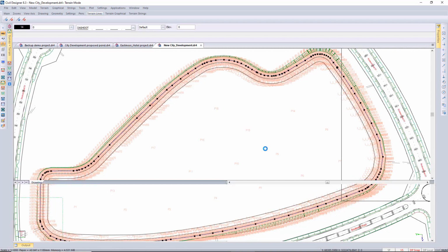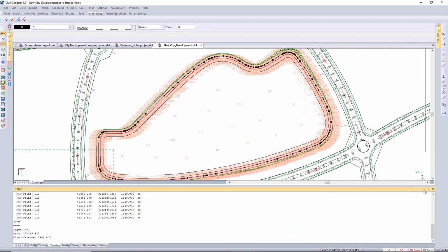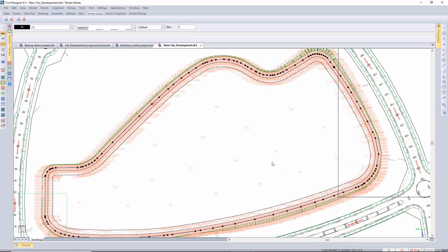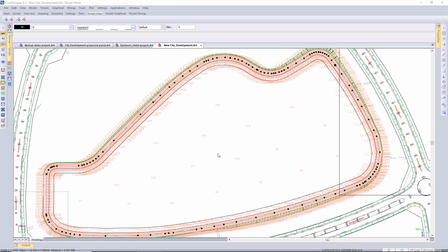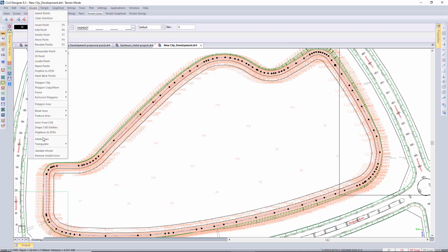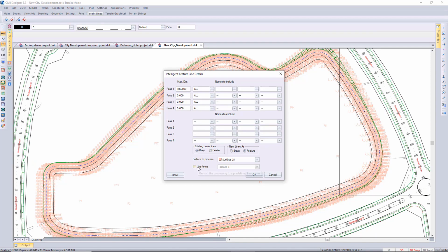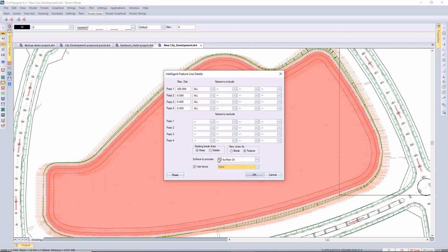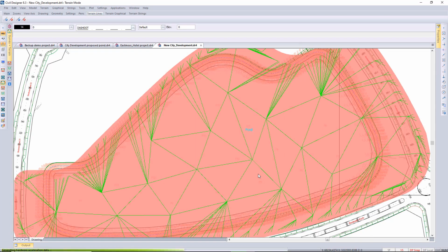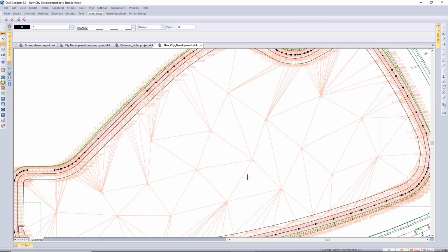Okay. So you can define as many of these fences to work with. So in this case, I want to use the defined fence in my IntelliLine triangulation. So model IntelliLines, and I'm going to confine the triangulation to this fence. There's a checkbox to use the fence, and in this case it's my pond fence. I'm keeping all the existing triangulation and just adding the new triangulation on the inside.